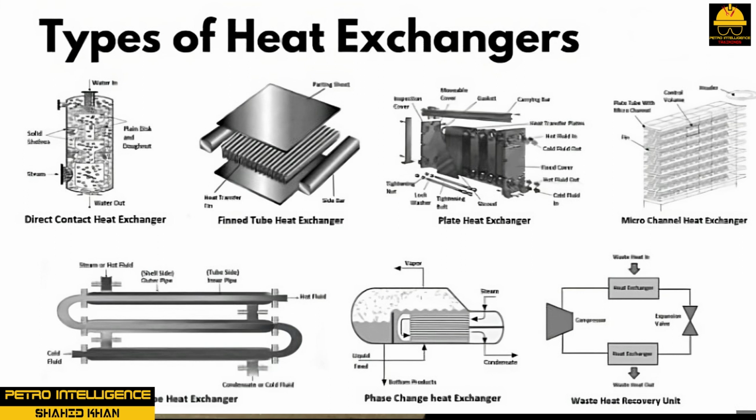The double pipe heat exchanger incorporates a tube within a tube design. It can be found with plain or externally finned tubes. Double pipe heat exchangers are typically used in series flow operations in high pressure applications up to 500 psi shell side and 5000 psi tube side.